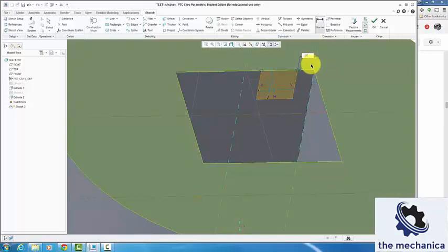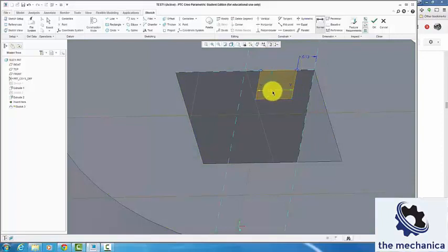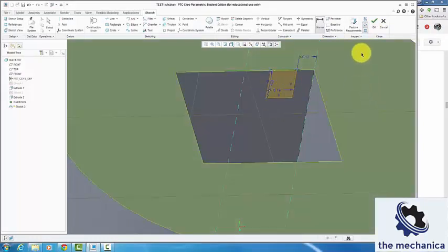If you're using a decimal equivalent of a fraction, just type in the full equivalent. Don't round it, because then you'll be off by 5 thousandths in this case. If I want this to be 3/16, I could also just type in 3/16, and it does it. So I can put those in. Now there are no weak dimensions left. Everything is a strong. It's what I want.